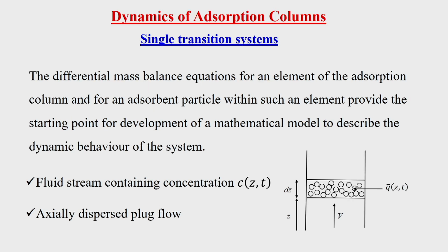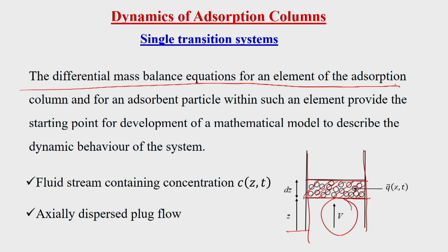Now we will be discussing briefly the dynamics of the adsorption column for single transition and multiple transition systems. Let us take this adsorption column, with differential thickness dz, and z increasing from bottom to top, with the velocity of the gas adsorbent as v. The differential mass balance equations for an element of the adsorption column and for an adsorbent particle within such an element provide the starting point for the development of a mathematical model to describe the dynamic behavior of the system.